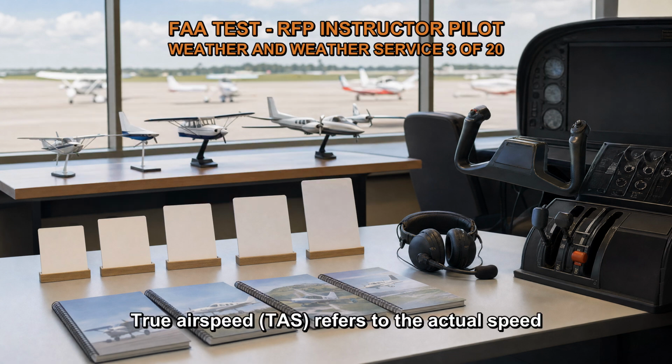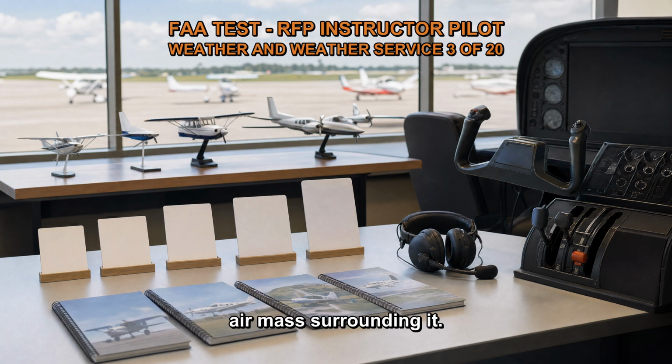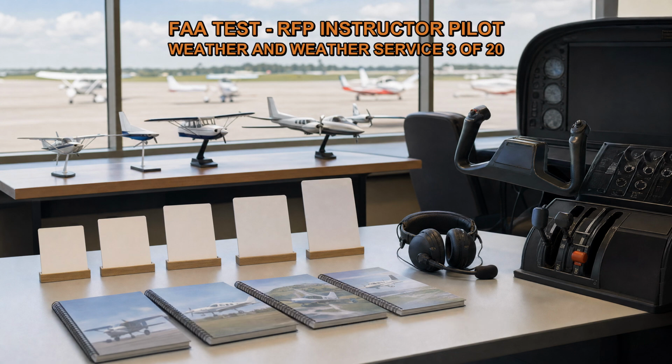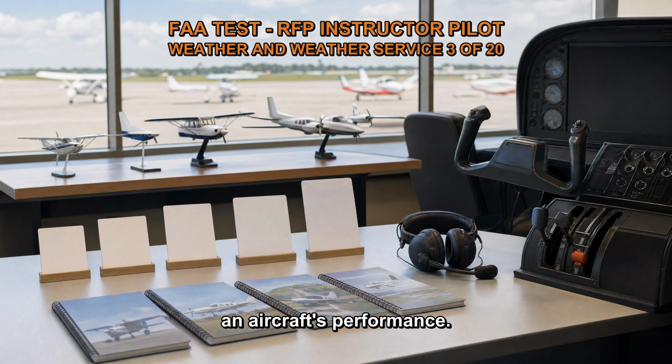True airspeed, TAS, refers to the actual speed of an aircraft through the air. It represents the aircraft's speed relative to the air mass surrounding it. True airspeed is affected by various factors, including air density, pressure, and temperature. As the OAT increases, it indicates that the air temperature is higher. Warmer air is less dense than colder air, leading to a decrease in air density. When air density decreases, it means there are fewer air molecules per unit of volume. This reduced air density has specific effects on an aircraft's performance.